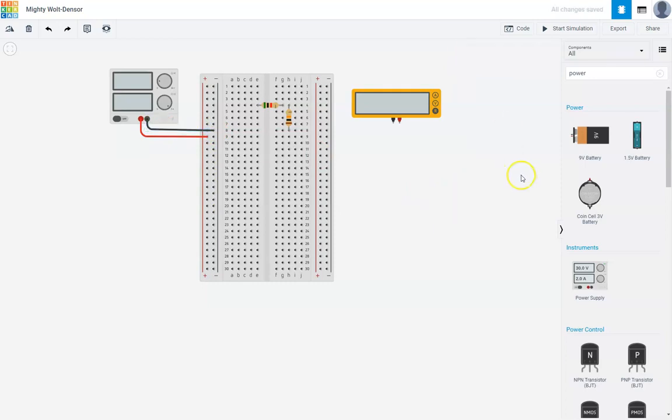Okay. Now from the power supply, this red power bar is all connected just like a real breadboard. So let's bring that power to that top resistor. I'll color that red. So power comes from the supply, goes through this resistor, and what we want now is from this resistor back to ground. So I'm going to bring it from this resistor back to ground right here, and I'm going to color this black. So I've created a full circuit right here.